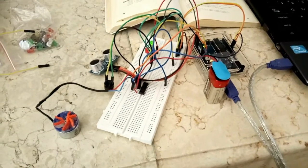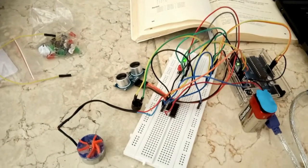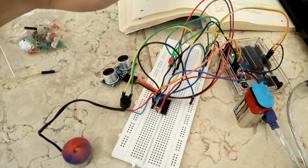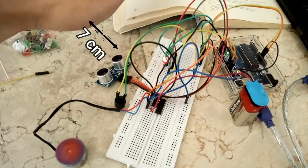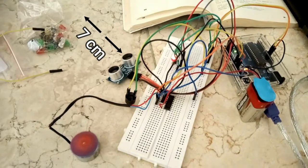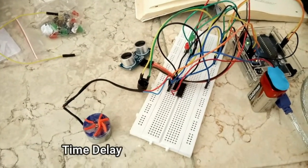Okay, watch carefully. You see the green LED is on as a standby indicator, then our hand is assumed to be a moving object with such a distance. And you see the red LED lights up to replace the green LED, which indicates the door must be opened through the reaction of a DC motor that rotates clockwise.